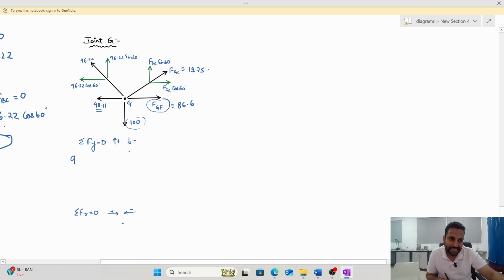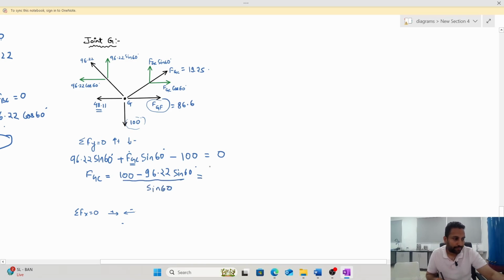So what is all going up? 96.22 sin 60 is going up, plus FGC sin 60 is going up, negative 100 is going down. Is anything else there in y direction? I don't think so. So it equals 0. So I can directly find out FGC is 100 minus 96.22 sin 60 divided by sin 60, which comes out to be close to 19.25 kilonewton, positive.